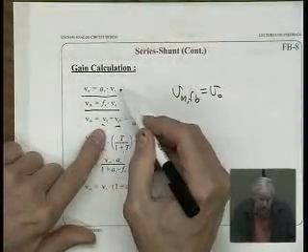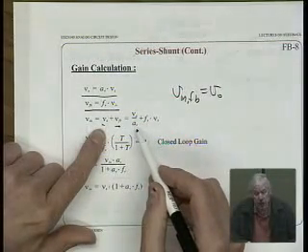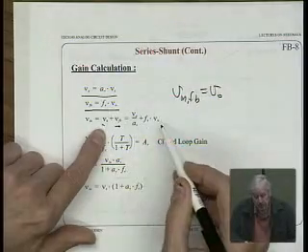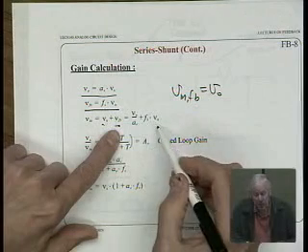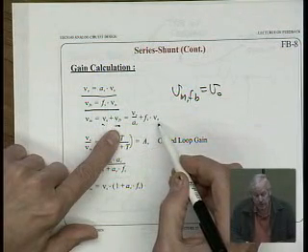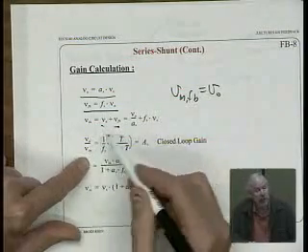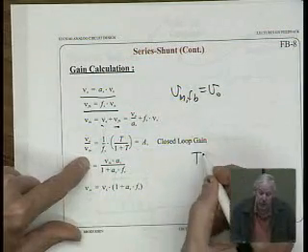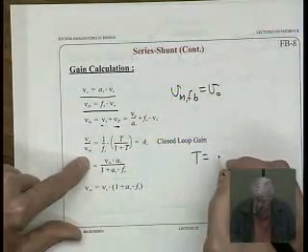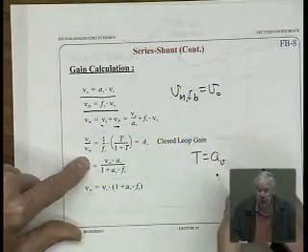But we can solve for V error from this equation. We get V out over the voltage gain of the open loop basic amplifier. V feedback is equal to FV, the feedback factor, times the output voltage. I can solve for V out over V in, and I get this formula that I solved last time: 1 over the feedback factor times T over 1 plus T. And remember, T was equal to the loop gain. T was equal to A of the basic amplifier.